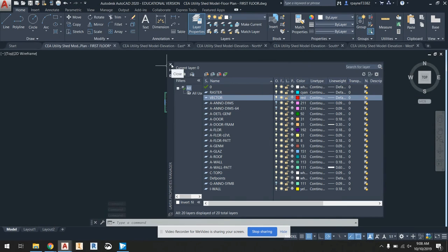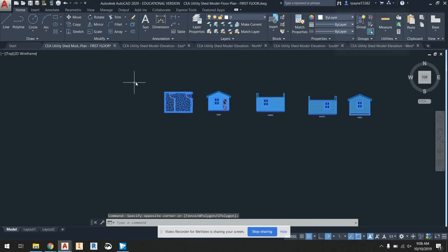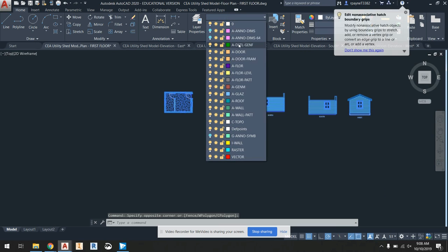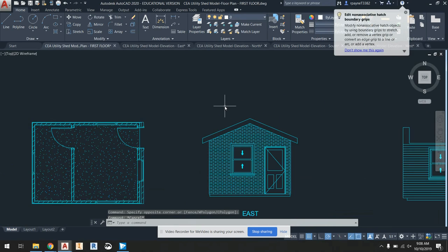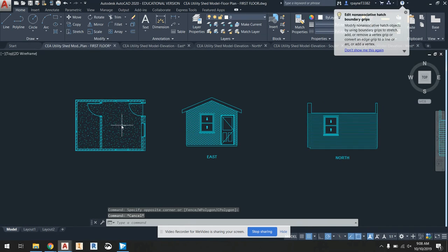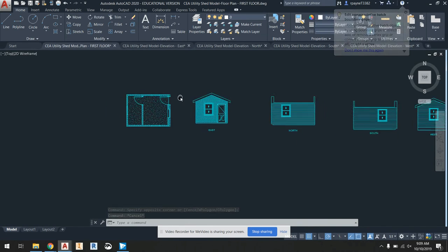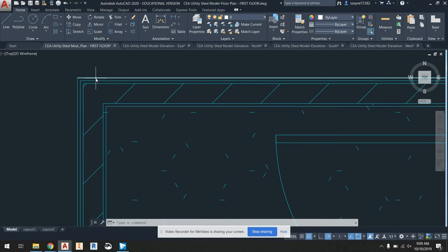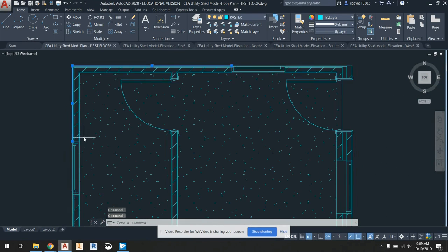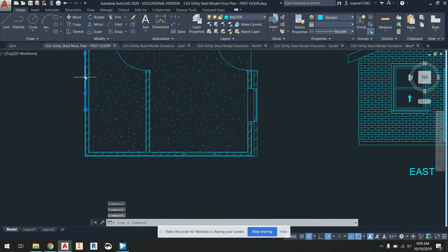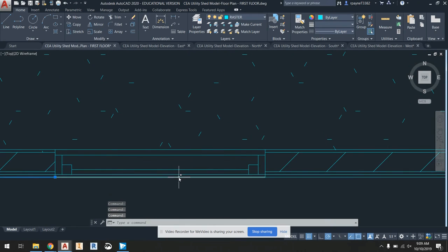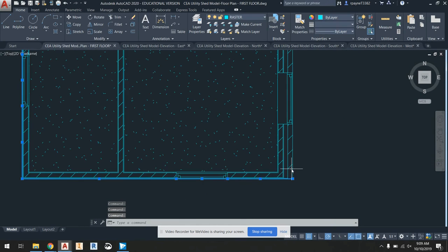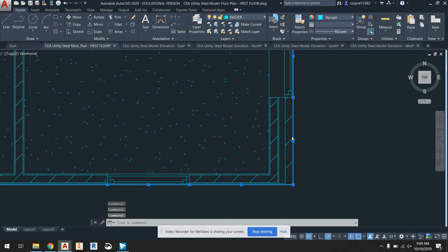Okay. So initially, we're going to change almost everything to raster, because almost everything we want to engrave. All right, that's all these individual things, and it's only the outline stuff, the stuff that's on the very outside edges. So you can start selecting those, the outside edges that we're going to vector. So I'm just going around selecting all the outside edges. I'm going to change those over to vector.